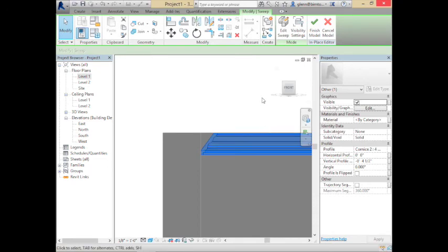if you have your target thing at the top there, and you change the shape you loaded to be below the target one, we'd have to define the profile a little differently. Now, the profiles are defined with the notion of where their insertion point is. So we could redefine the profile, moving the target insertion point up to the top, and then it would be a downward profile as opposed to an upward profile. If I was doing this a lot, that would be the way to do it, because that would really give you more power.